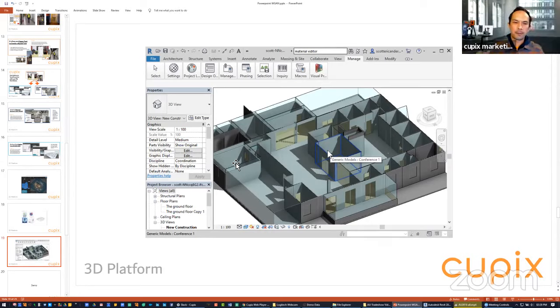So quite a bit different than a nice looking blob, albeit when you're far away, a blob of a dollhouse view. And you'll find a mesh model. We create a mesh model also, from Matterport. It's not something you can use in Revit or AutoCAD or other architectural programs. You would need to use it as the template to trace over, but you would have to put it into BIM objects, because that's just not usable. You can't use a wall that's made up of, let's say, 1,000 faces. It's just not usable within a CAD program.